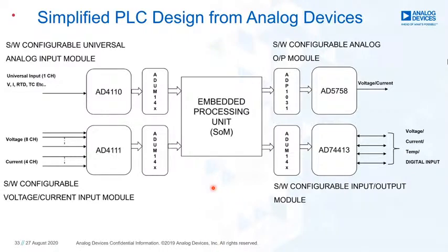Yes. So when we compare analog and digital isolation, analog isolation is a traditional way of isolating the input signals. Usually we use linear optocouplers for this particular application. The disadvantage or the concern with that is, when you use an optocoupler for this kind of application, first, it's power consuming.